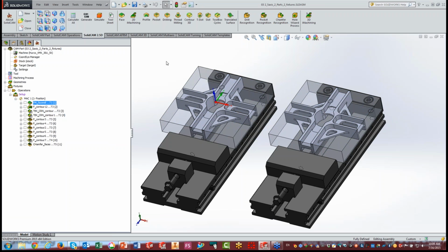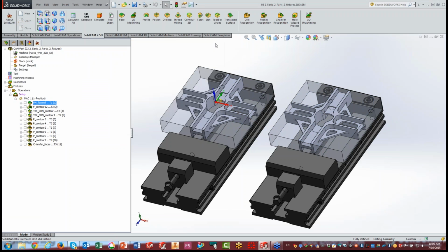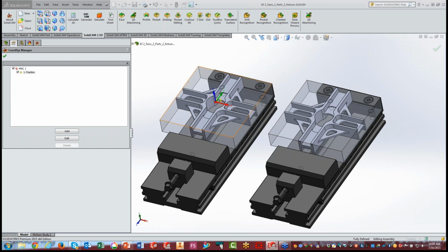What we've done is as follows. First of all, we've added an option for creating according to, if I go back to transform, coordinate systems. But before that, I have to make sure I have another coordinate system on this part. So let's go into my coordinate system manager. And right now, all I have is one coordinate system. Okay? So I have to create another one.